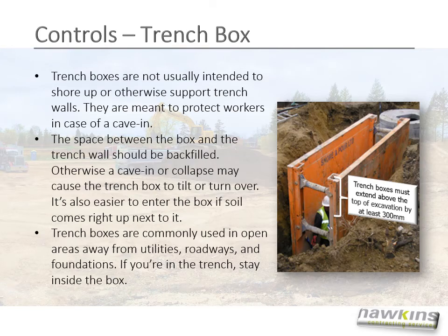The third control option for addressing the risk of collapse is a trench box. Trench boxes are not usually intended to shore up or otherwise support trench walls. They are meant to protect workers in case of a cave-in. The space between the box and the trench wall should be backfilled. Otherwise, a cave-in or collapse may cause the trench box to tilt or turn over.